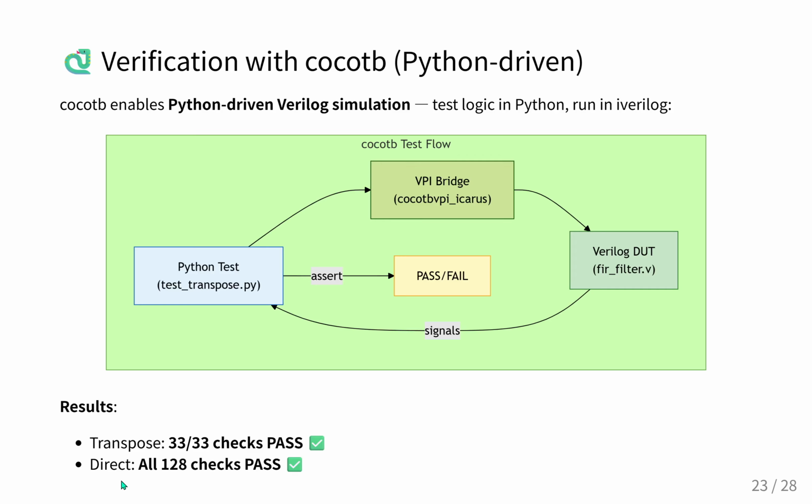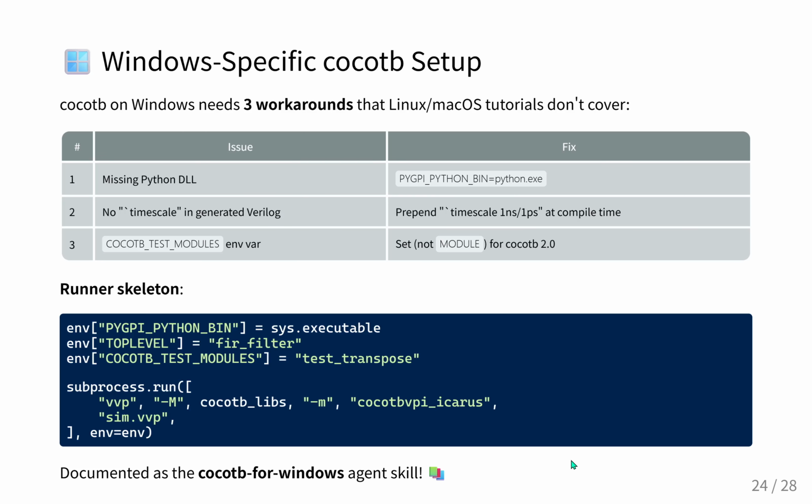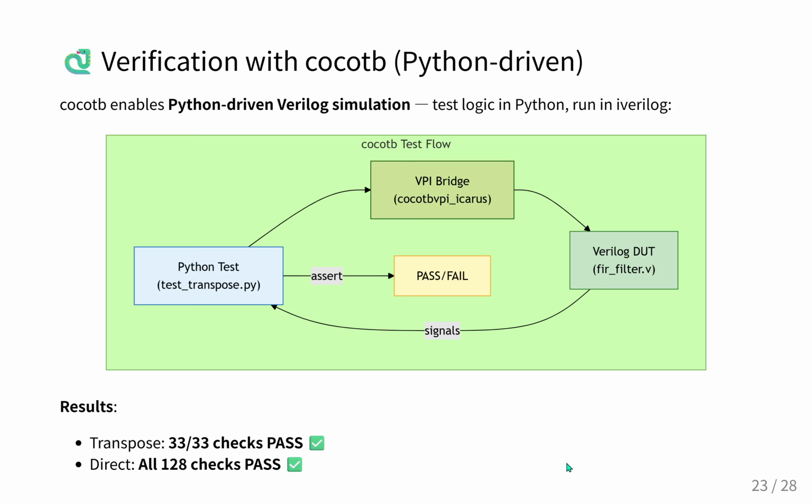Because direct form is just combinational logic with no memory and no clock. You don't test it over time. You can't. Right. So instead, they fed 4 distinct static input values into the system and simultaneously checked the raw output across all 32 taps. Just instantly reading the wires. Exactly. And 4 inputs times 32 taps equals 128 separate mathematical checks.